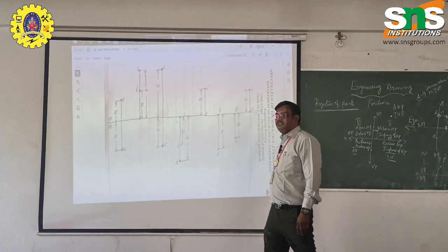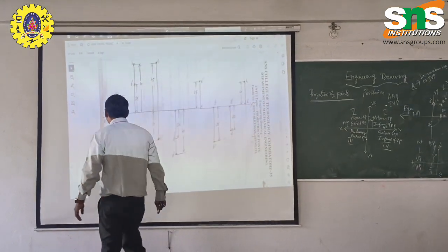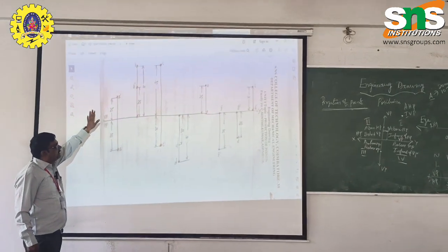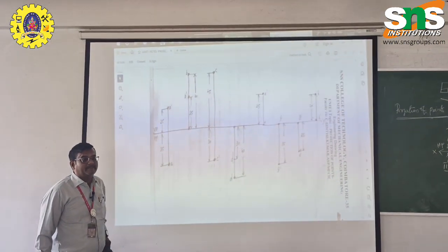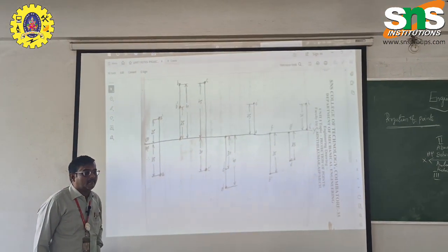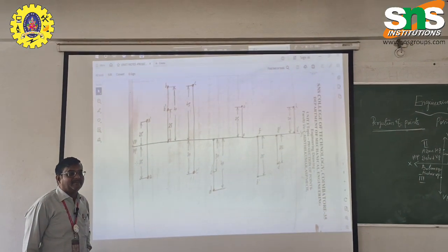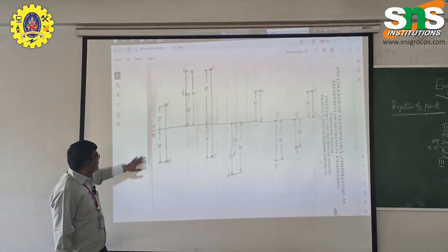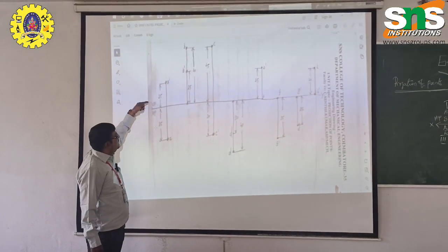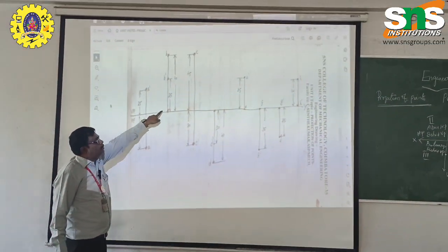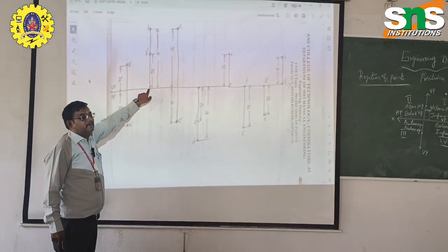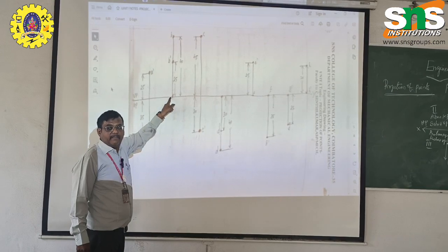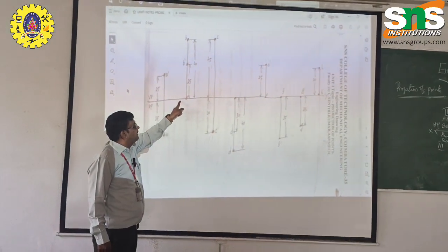So here, the first problem, what they said, the first quadrant. Here, there is a mistake. What is the common mistake I have made in this problem? Tell me. This is called brainstorming. What mistake is there? This is the first quadrant. VP is here, HP is here. This is supposed to be the second quadrant. VP and HP have to be written here.